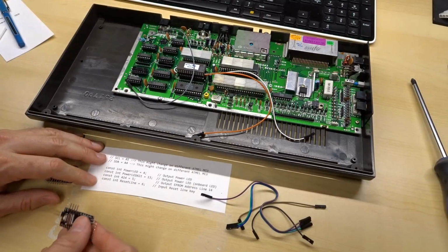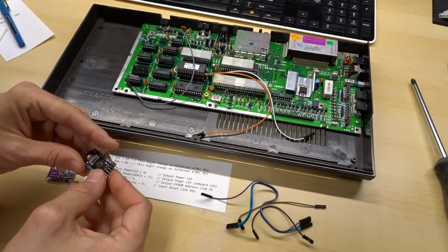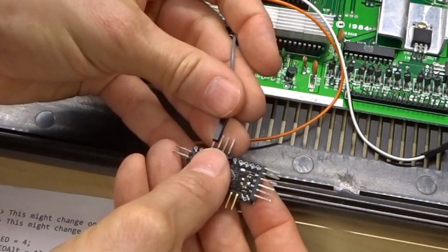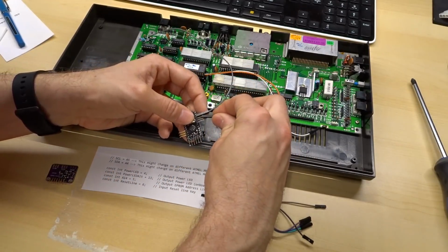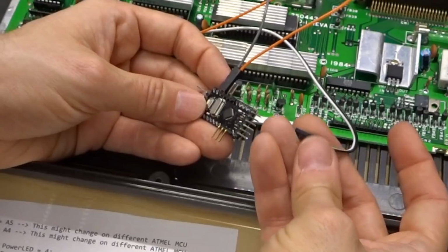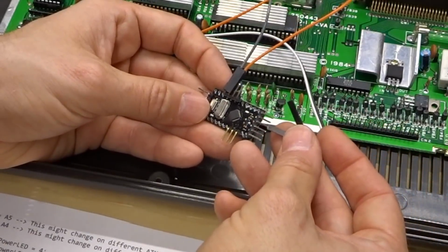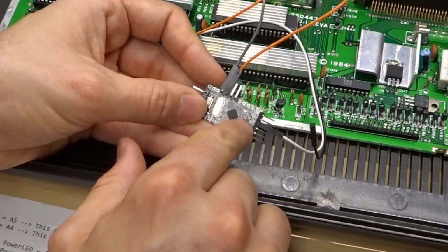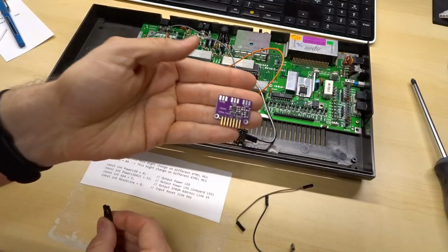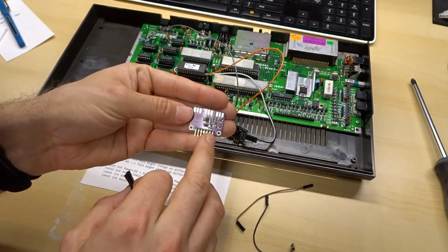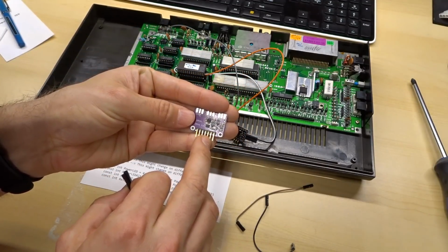All right, so on the cheat sheet, reset line is pin 6. So that's this one. A14 is pin 5, so A14 is this orange wire. VCC for me is the white wire coming off the EEPROM socket, so I'm going to plug it onto VCC, and ground will go onto ground. So on this little board, we need to hook up VIN, ground, and the 2 serial control lines.